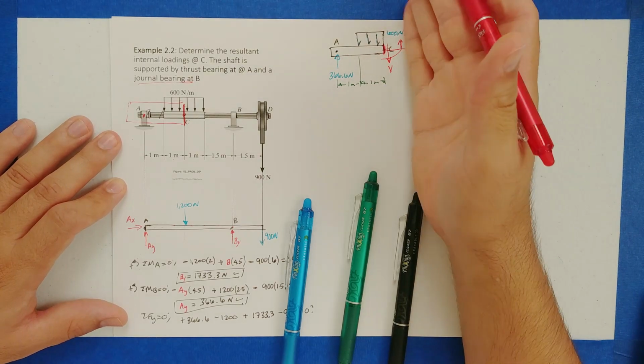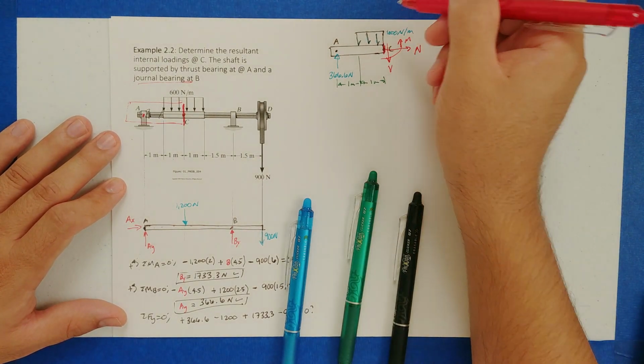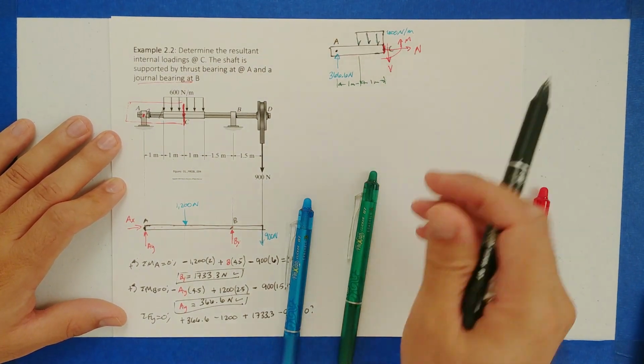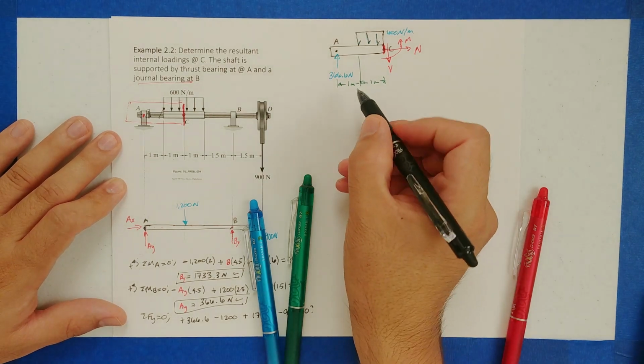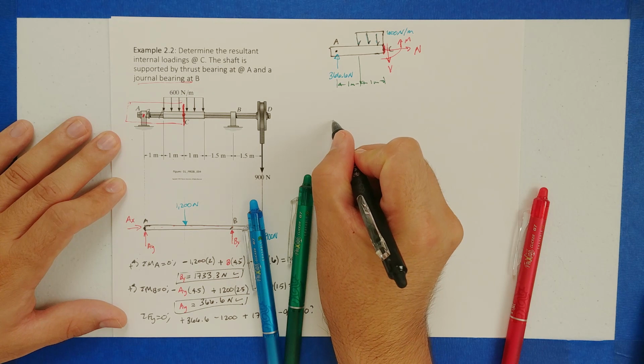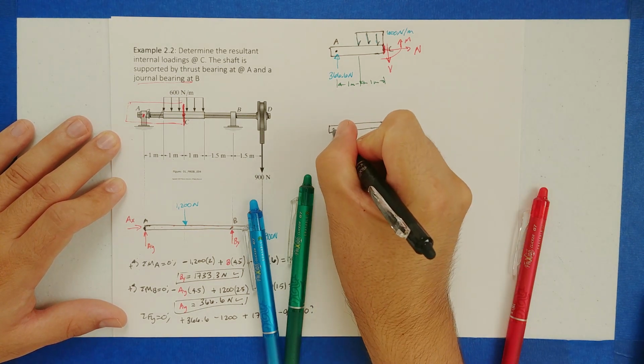It would be on this right-hand cut, counterclockwise. But I have the distributed loading. So I guess I could use this one. Or rather, what I would do is just go ahead and simplify this distributed load into a point load. Here's how to do that. Again, here's free body diagram number 3. Here's our point A.